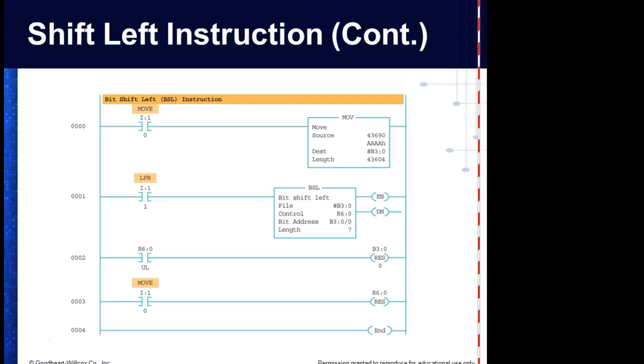So up here I say, okay, I'm going to shift left some file somewhere. So this cannot be a constant. This cannot use immediate addressing. Can't even use direct addressing, because it says we must use index addressing. So it's going to take whatever's in the index register, which is S24 inside the status file, and it's going to add this register. And that's going to be the address of the object.